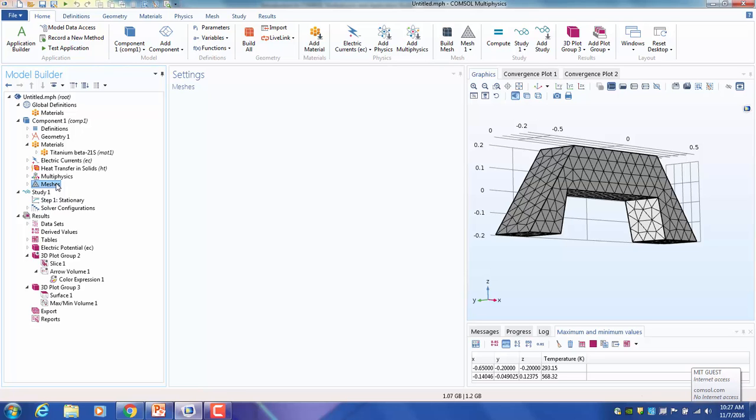Then refine the mesh a couple of times, actually more than a couple of times, and make sure that the solution doesn't change with the mesh density. Then you know you've eliminated the numerical artifacts and you're looking at the converged solution. Of course, engineers have different error tolerances, so you'll see the asymptotic limits as you refine the mesh, and then you can decide, I'll just use less memory and be happy with that 5% error. That is your call in terms of how fine you eventually want to mesh the geometry.